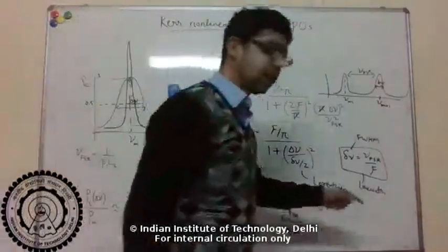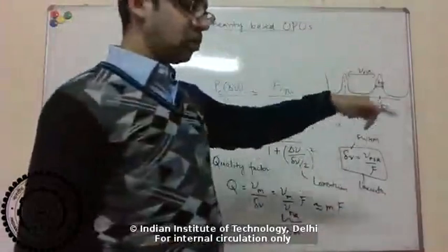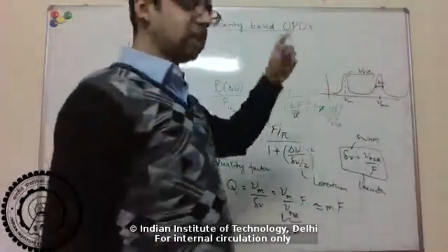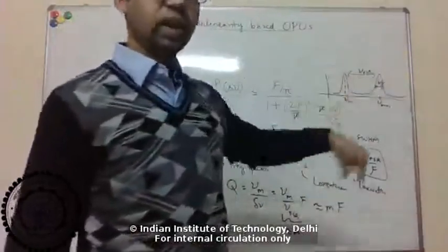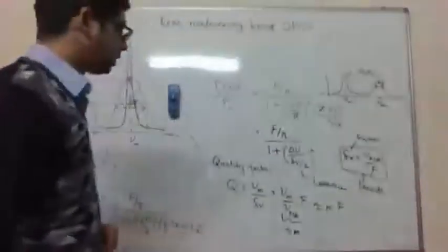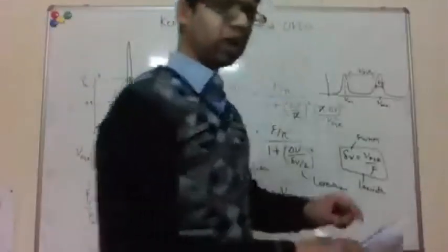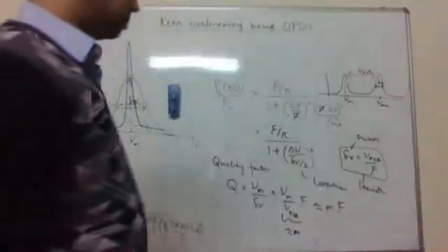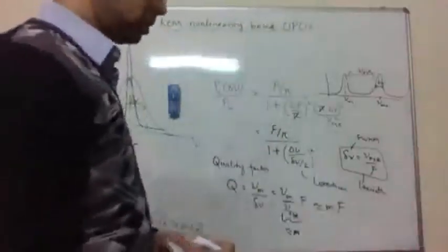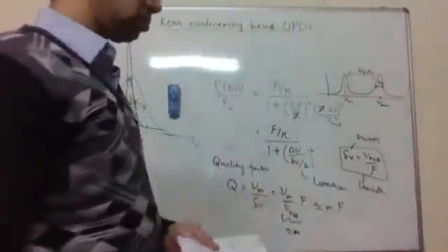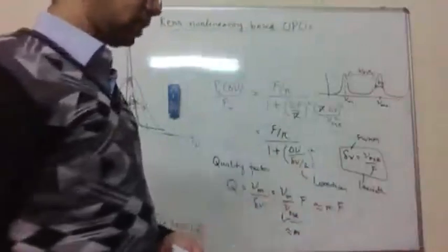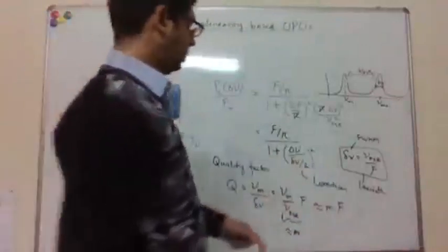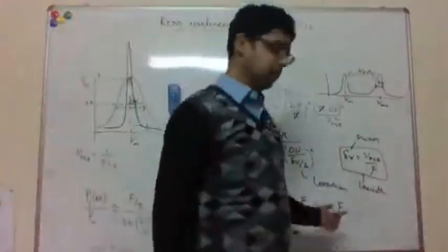Right, so this mode number was basically how many multiples of 2 pi phase you are getting, or in other words, you can think of how many wavelengths are fitting within the round trip of the cavity, right? So this m is usually, even for micro resonators where the diameter is sort of 100 microns on that scale, so the circumference is roughly, let's say, a millimeter, this m is typically a big number, like 1,000 or so, even for the smallest cavities.